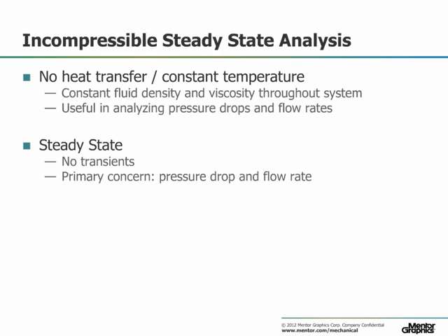The benefit of running a steady-state analysis as opposed to a transient is speed of simulation. The steady-state analysis will run very quickly and allow engineers to run more what-if scenarios in a short amount of time.